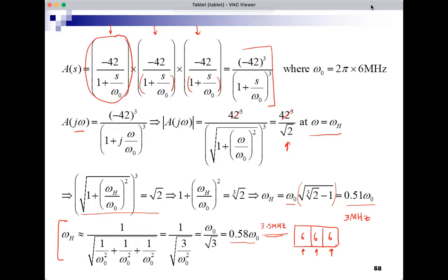In some kinds of amplifiers, this is almost a constant. So the gain bandwidth product is almost constant, which means that it's up to you to decide. If you want more gain, you will get less bandwidth, and if you want less gain, you can get more bandwidth, and the product is almost constant. So we'll return to this topic later.